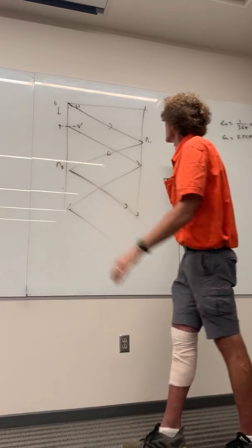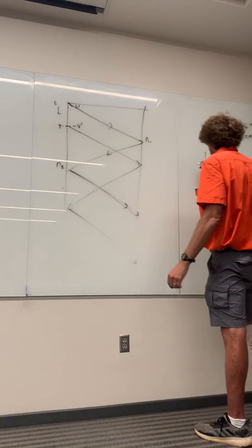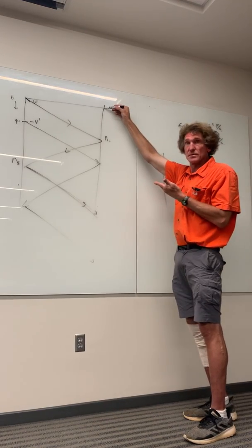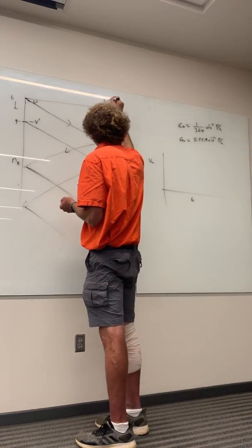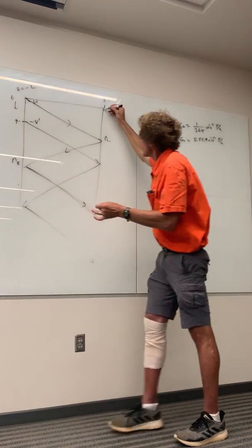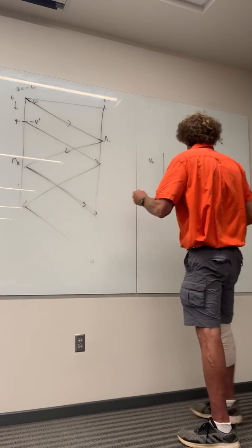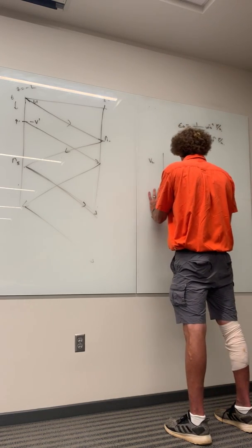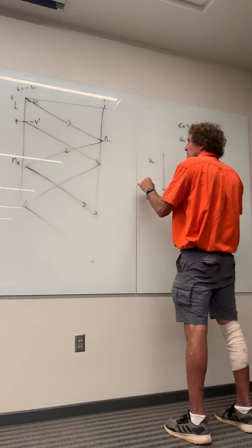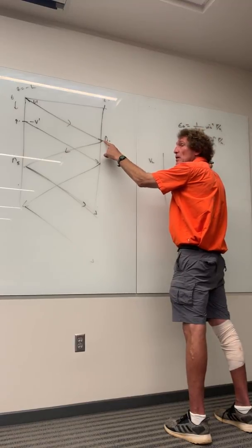Now, if I want the voltage, say, at the load, and I want to graph it, this is going to be V at the load versus time. I start here because this is where the load is, right? This is Z equals 0, and this is Z equals minus L. I come down here, it's 0 until one time constant, whatever the time constant is, I'll just call it TD. And then it goes up to what? Not V prime, but V prime times gamma L plus 1, right?